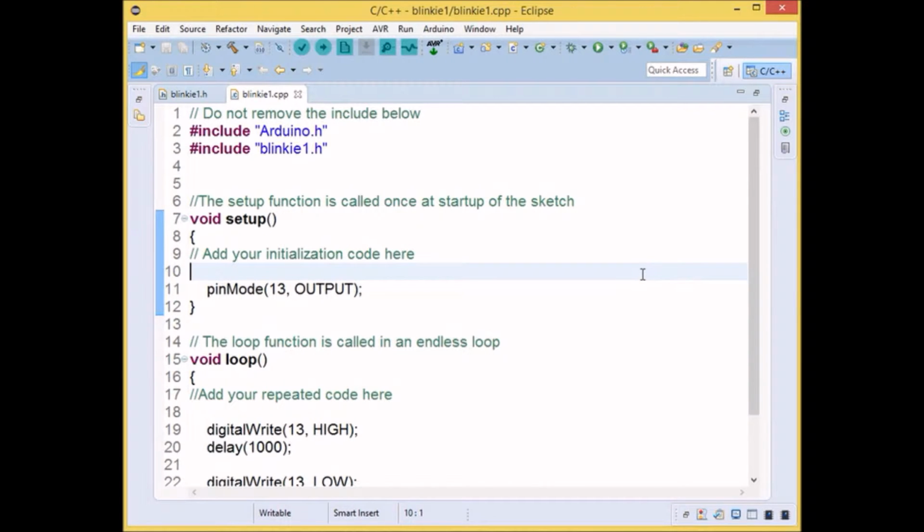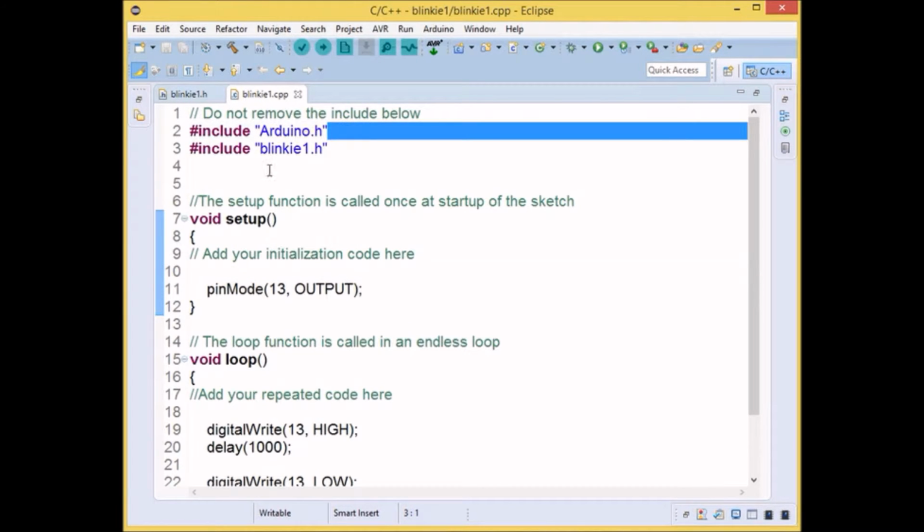So let's go to the .cpp file, which is our source file for our main class here, in which this is our main class here. Now notice, we bring our Arduino.h file into this file. It may not be needed. Here's just something I do, because I do know a lot of times when you don't include it, there'll be a problem because it doesn't pull the way it wants to pull. So I just bring it over. It couldn't hurt anything. We have our Blinky1.h, if you'll notice. Okay, so what that is saying is we're pulling from our header file.